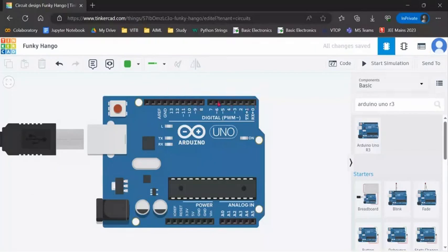So if you want to use any sensor or any input and output that is related to digital input and output conditions, we will be utilizing these terminals. Where it is written digital, starting with 0 to 13. Similarly, in this case, analog inputs are the content. Here A0, A1, A2, A3, A4, A5 are considered the analog inputs and outputs.